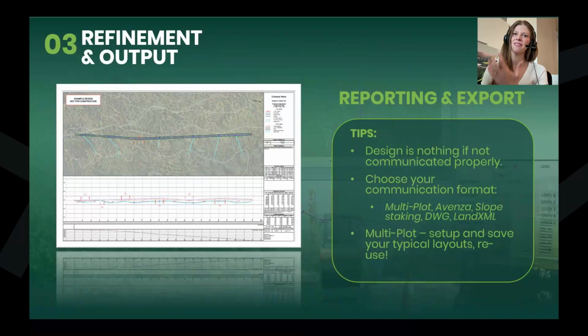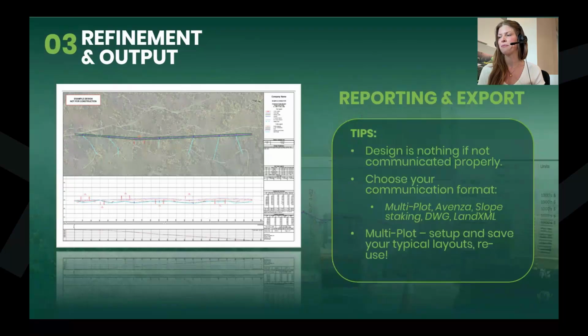And then finally, as you can see here on the screen, for those of you new to RoadEng, our construction documentation editor is called Multiplot. And like most of the software, it's super reusable. Once you figure out what works for you, like Matt's screen layout, he's saved it and then he can call it and reuse it. We can literally do the same thing with multi-plots. So you can save your formats, call them, reuse them, and then start to get a whole bunch of design efficiencies by leveraging these templates, these defaults that you've set up.